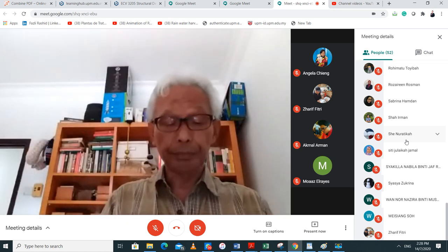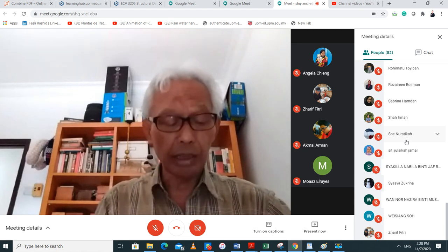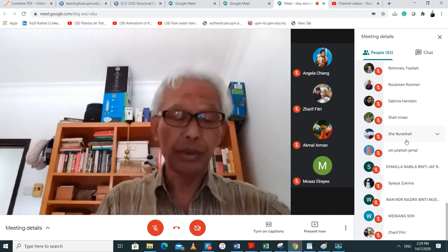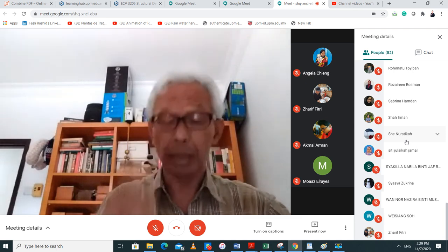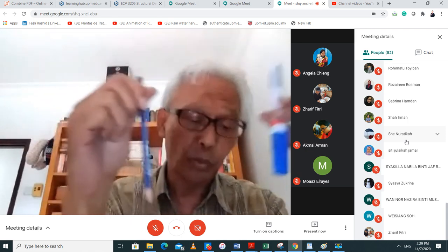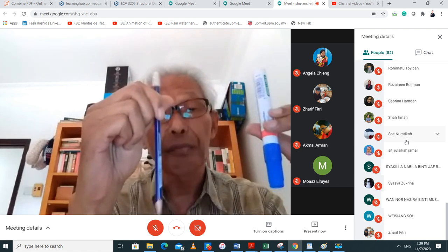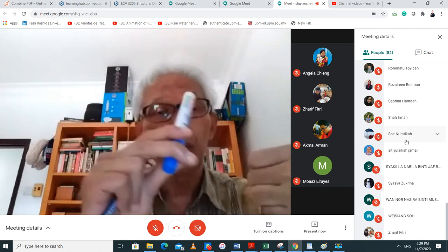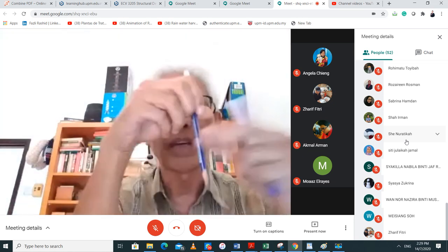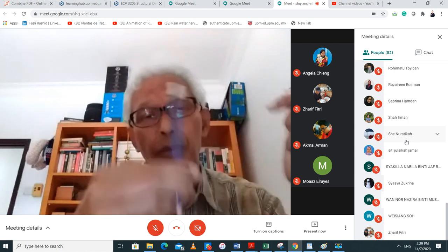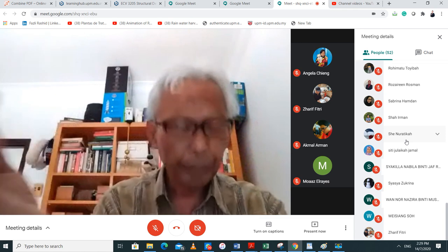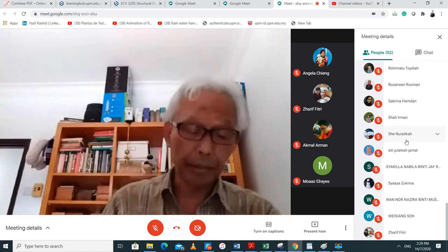The other one, if you take the shaft friction from the penetrometer, is equal to 2 times the F sub C, which is the cone penetrometer. Pile F sub S equals 2 times F sub C if you ever have the shaft friction of the penetrometer. So the first one, you can have Q sub C bar average divided by 200. The second one, if you have all these F sub C, the shaft friction from the penetrometer, you can take all of these values, multiply by 2, and use it for the pile. So those are the empirical equations.